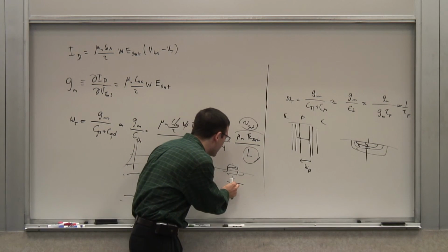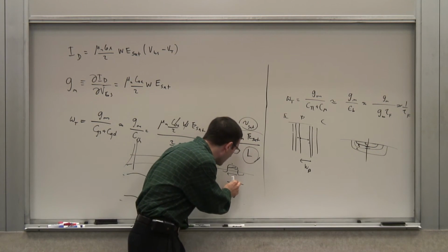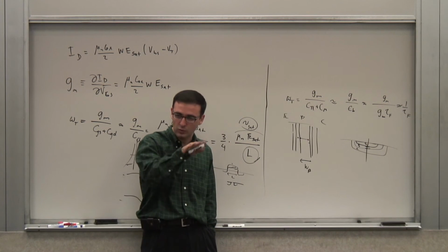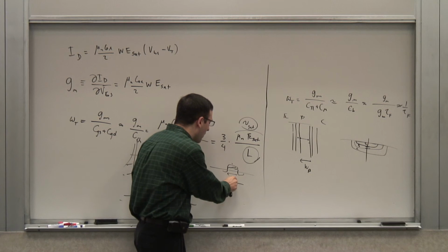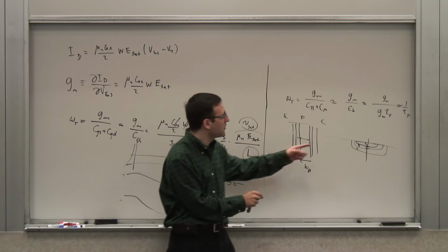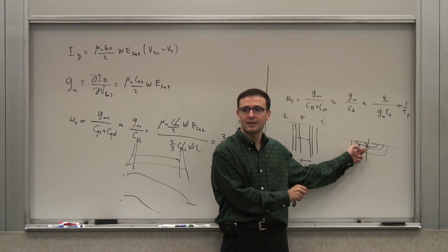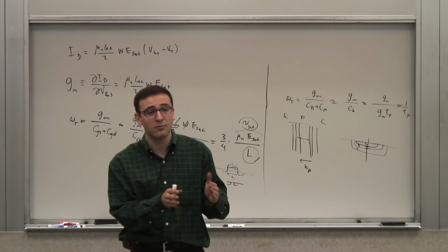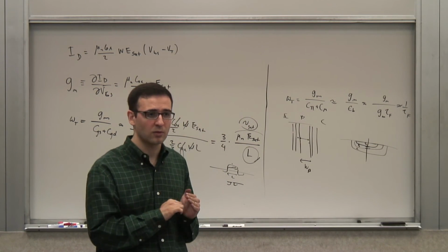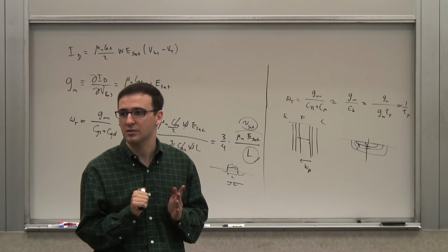So that's really limited by the lithography, how fine you can control this process of fabricating this, which we'll see next time, how it's done. So the finer you can make this, the closer you can bring it to this. And that's how they've been catching up. They have finer and finer lithography. And MOSFETs today are much closer to bipolars than they were 10, 15 years ago.